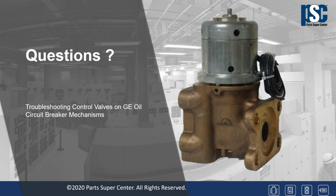It's a fixture that fits on top of the valve, and it's actuated by the plunger on top of the control valve, the coil valve housing, and it operates a cycle timer, and it shows that the valve is actually shifting to the open position and closed position in the prescribed time. We don't publish those times because there's no way to really test that in the field.